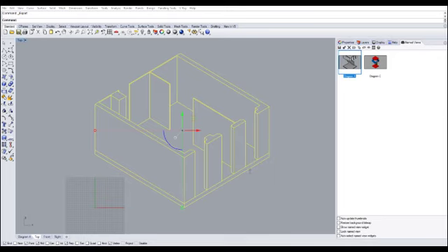Now we're not done yet. You're going to click on Options. Snap to Current View is on by default. Make sure your Preserve Model Scale is on. And if you recall, we've been making our survey plan in 1/4 inch equals 1 foot, which is 12 inches.